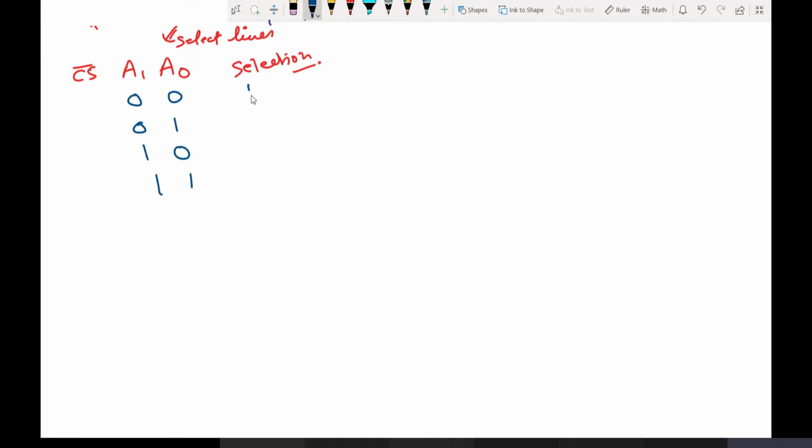The selection is, there are many things inside port A, port B, port C. So how are we going to select port A, port B, port C? Is there any way? Are we provided with any kind of switch? No, we are not provided with anything. This is the decoding table by which your port A, port B and port C will be selected.